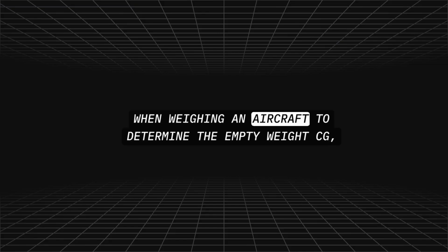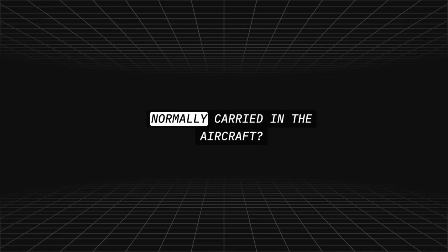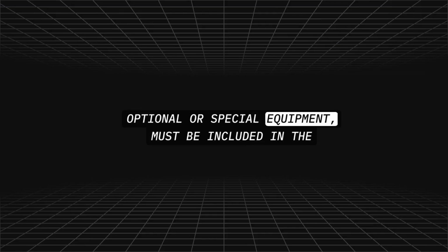When weighing an aircraft to determine the empty weight CG, what must you do regarding the fixed equipment which is normally carried in the aircraft? All operations equipment, whether it is required, optional, or special equipment, must be included in the aircraft's empty weight.